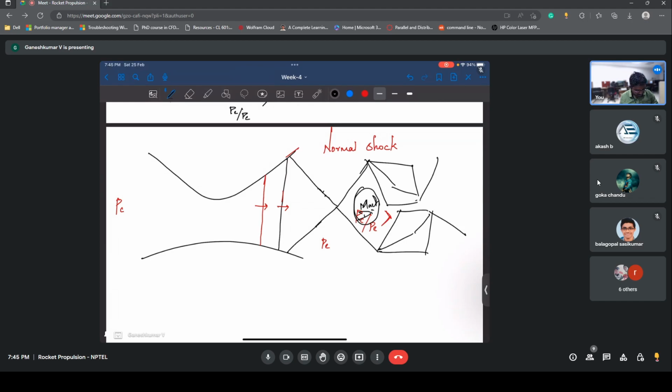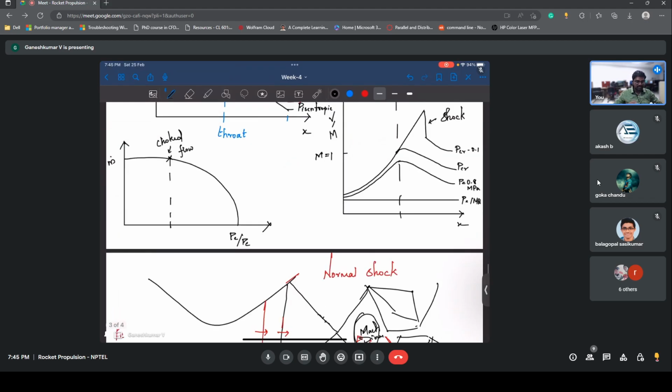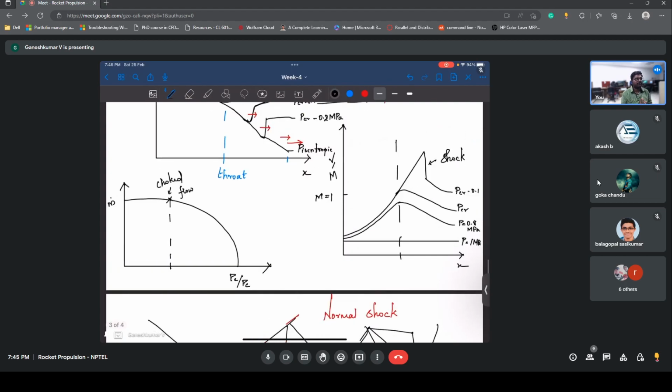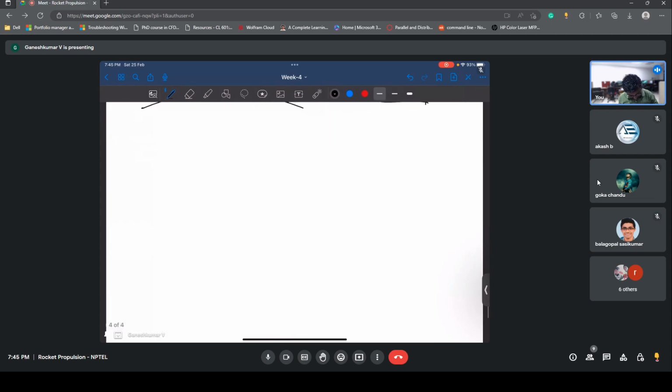So these diamonds happen as the normal shock gets out: if your pressure gradient is not able to withstand a normal shock, it puts an oblique shock. Once the oblique shock has formed, because of the conservation of mass at the nozzle end, the waves just reflect within that domain. If you are interested in more details, you can look further.